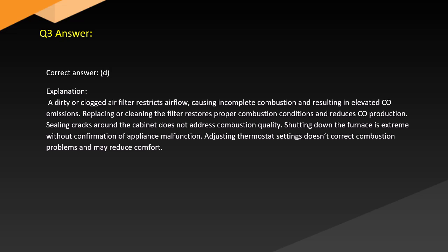Answer. Correct answer: D. Explanation. A dirty or clogged air filter restricts airflow, causing incomplete combustion and resulting in elevated CO emissions. Replacing or cleaning the filter restores proper combustion conditions and reduces CO production.